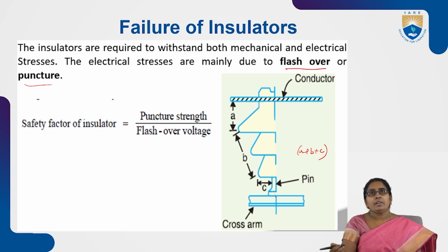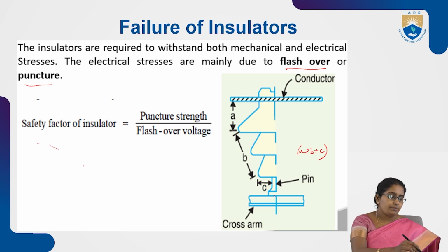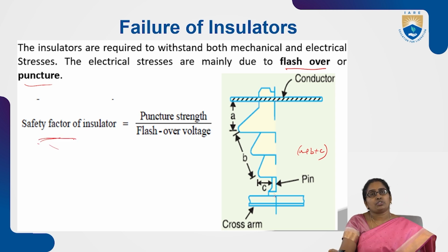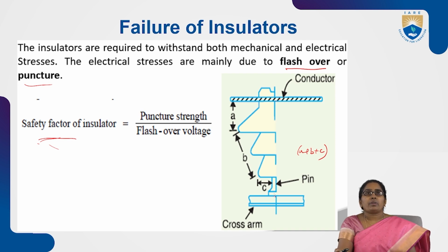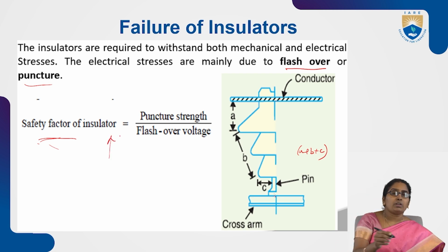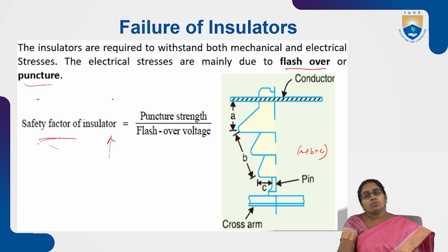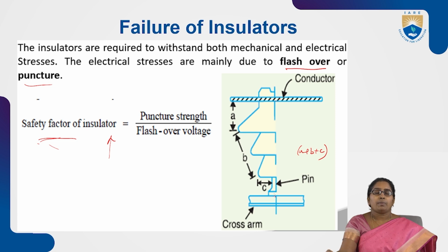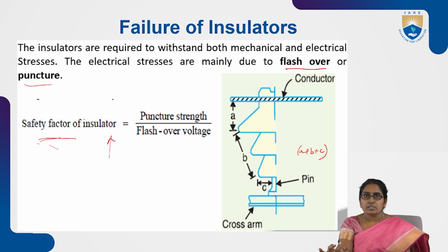Generally, there is a factor they define, safety factor, in terms of this puncture and flashover. Safety factor is defined as puncture strength to flashover voltage, okay. And this value is generally very high. So the flashover will take place before the puncture occurs.